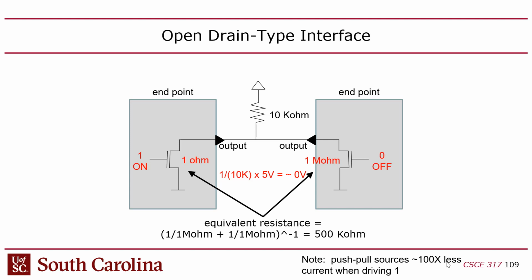But then you might say, wait a second, hold on. Now you basically have a short circuit here between ground and VDD, which you do, except it's through this pull-up resistor. So you're going to end up with about half a milliamp flowing down through here, which isn't too bad. That's manageable. It's more than the microamp we get in leakage, but it's a lot more than we get with a push-pull style driver, but it's manageable, right? And so that allows us to put a 1 in here, which will then put a 0 out as the output on this guy.